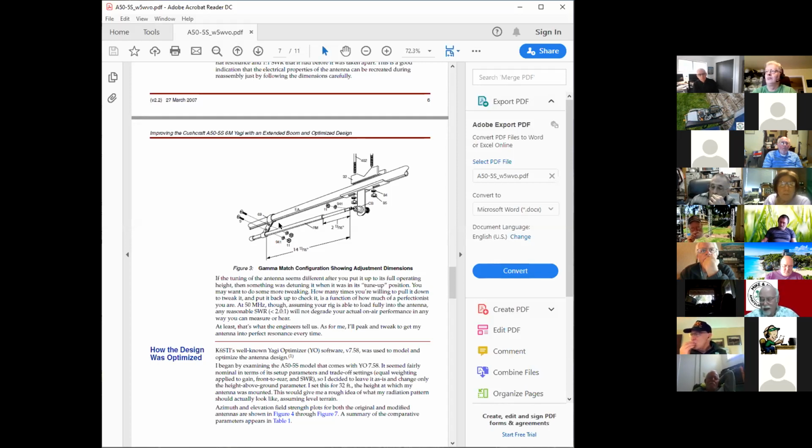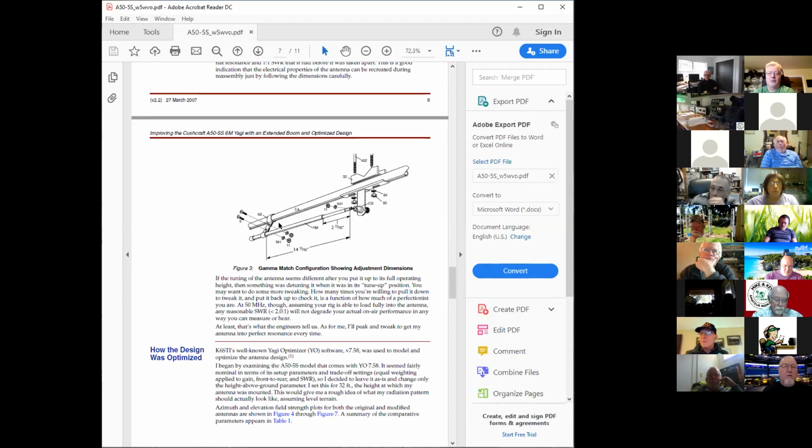Okay. The actual thing that will match the 12 ohm Yagi is called the DK7ZB match. DK, Delta Kilo 7 Zulu Bravo match for Yagis. It uses 2 parallel coaxial loops to match the antenna. This is a very popular match for 2 meters. I probably have 2 antennas down in the garage that have this match on it. So I would recommend that you look that up as the way to match instead of using a gamma match. But we do use gamma matches all the time.